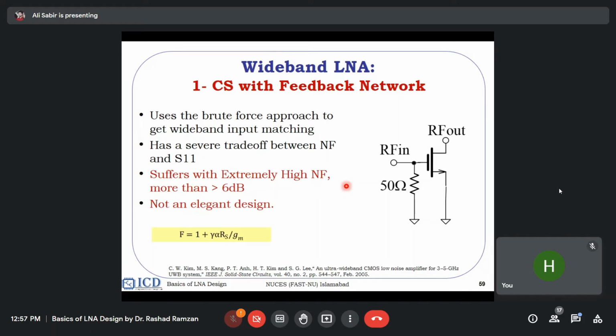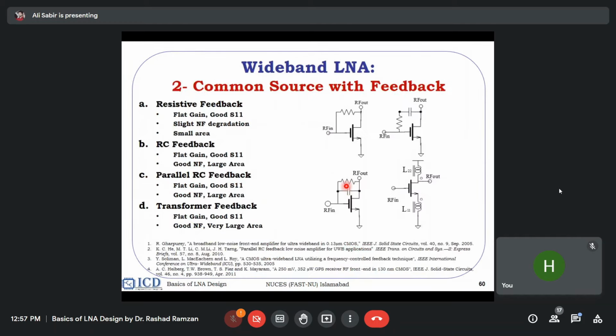So, CS with a feedback network. This is an LNA where you can put a 50 ohm resistor to do the matching. What's the disadvantage of this type of network? You are doing the 50 ohm matching and you have just placed the 50 ohm resistor at the input. Noise figure will increase, power consumption will increase. Noise figure is the biggest disadvantage. We cannot do that. So what are the possible ways? It is the feedback, in these three different topologies.